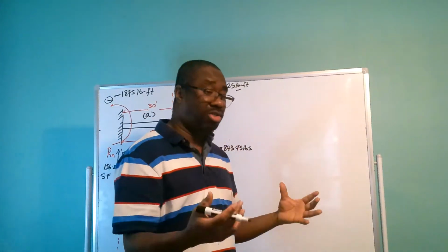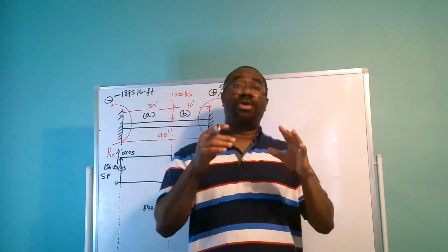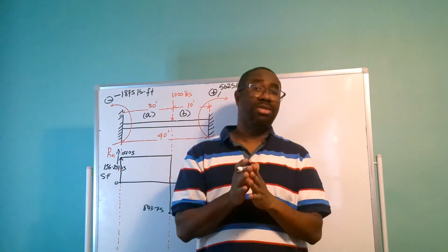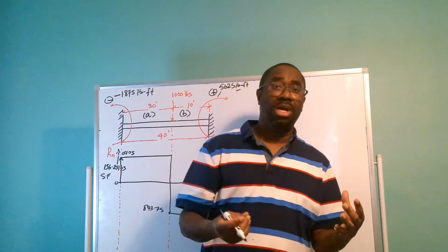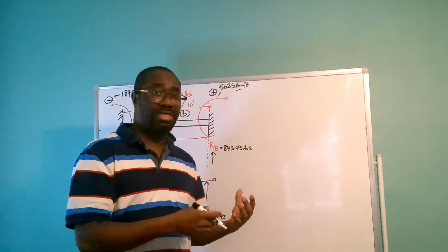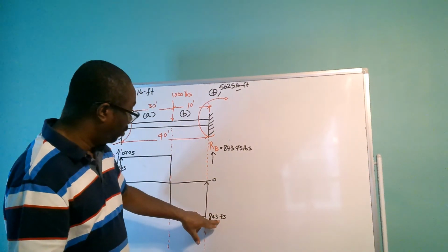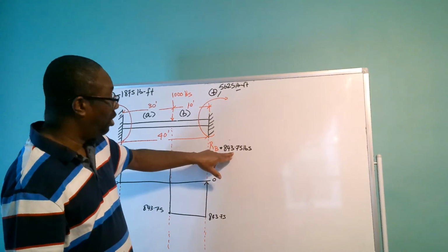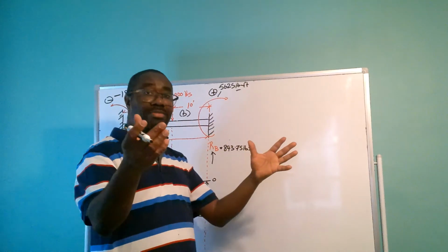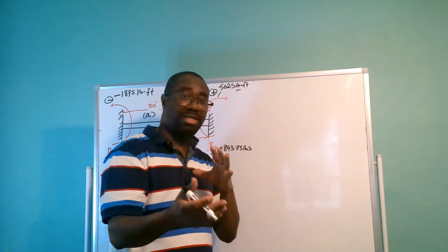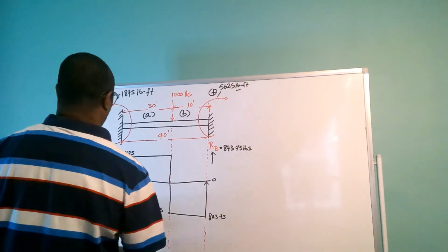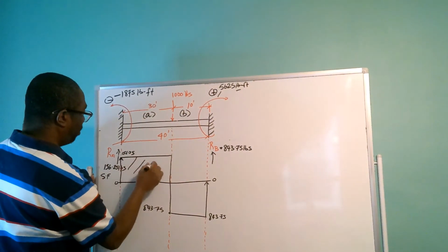And as I mentioned to you before, if you're plotting your shear force diagram and you do not get your shear force diagram to close, you do not get this load here to equal to this load here, you have done something wrong and you need to recalculate again. So our shear force diagram will look something like this.